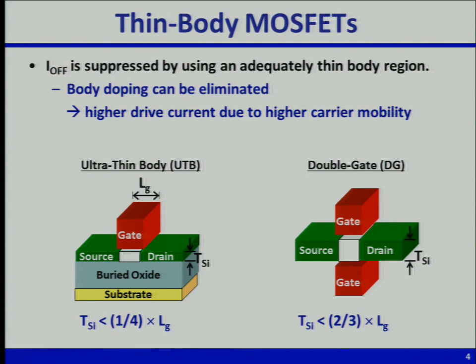And what's worse is that this quantum confinement is quite sensitive to the thickness of the silicon. So in a manufacturing process, if you have 2.5 nanometer thick silicon and you have plus or minus a few angstroms of variation across a wafer, that will lead to significant variations in the threshold voltage. And that's not really acceptable if you want to design a circuit to meet your power constraints or your speed performance requirements. So ultimately, we knew that the thin body device couldn't be scaled. It's not going to be easy to scale that below 10 nanometer gate length.